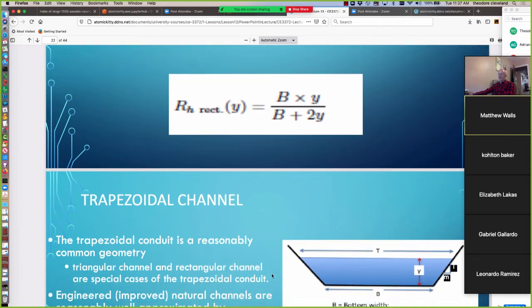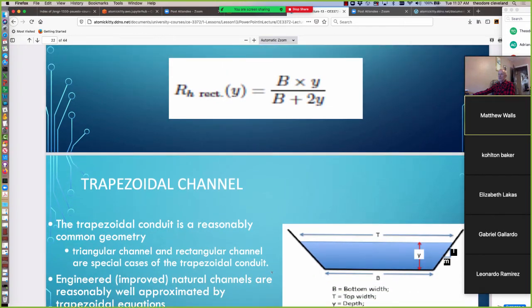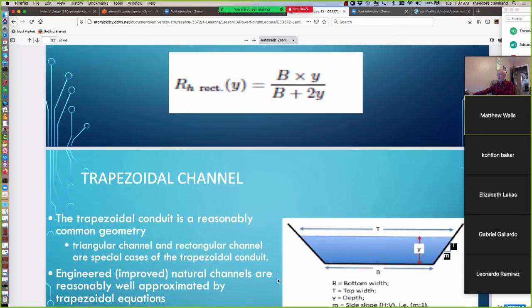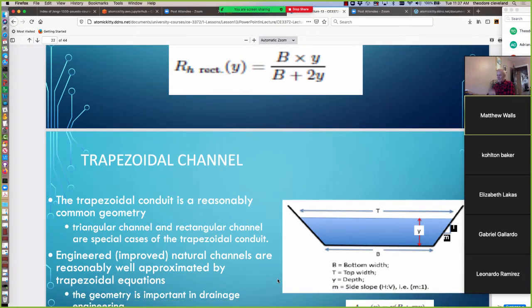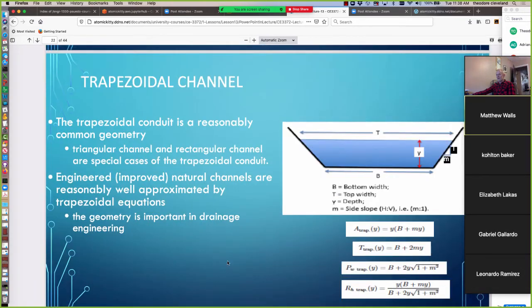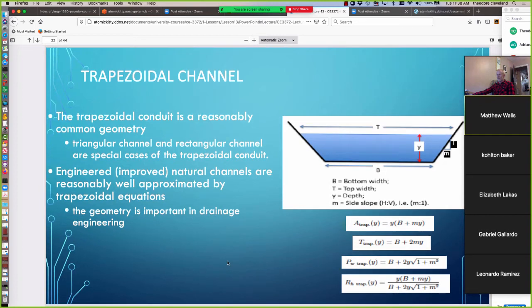So as a way to keep in mind, if you've selected a hydraulic radius correctly, its numerical value shouldn't ever get much bigger than the flow depth, and probably is kind of close to flow depth. Not close enough that you want to write it down and get sued because your project failed, but just as a rule of thumb, it shouldn't vary hugely from whatever the flow depth is.